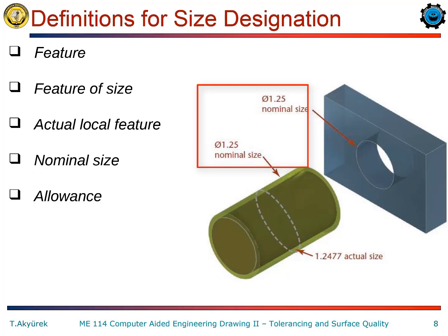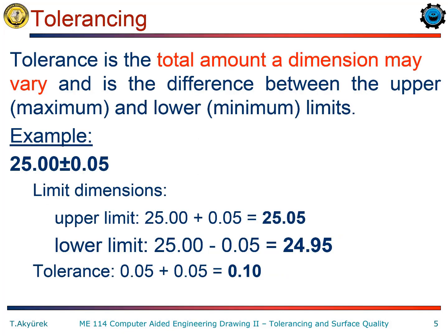We consider this functionality under three main topics. A connection can be defined as a clearance fit connection for easy assembly, or it can be defined as a sticky fit, which is called transition fit. Finally, the parts can be defined as interference into each other, which is interference fit. We will talk about this in detail later. Tolerance between parts should be applied after the decision has been made based on the functionality.